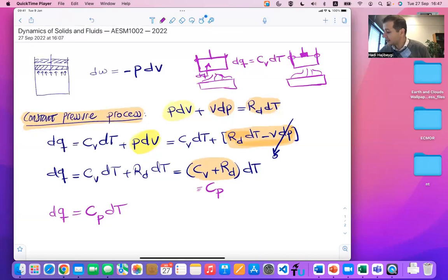And if I add heat on it, it actually expands too. So it comes to a higher level with this amount. That process will cause the heat added to the system to go through Cp dT, the constant pressure heat capacity. Constant pressure heat capacity, as you can see here, is bigger than constant volume heat capacity, which means Cp is bigger than Cv.